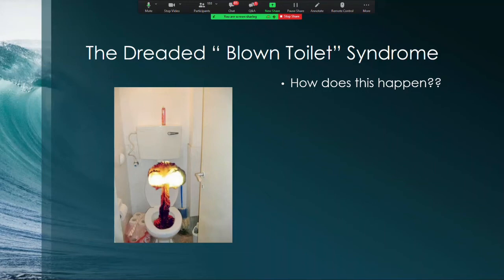So I'm trying to shove an 8-inch column of air through a 5 or a 4-inch orifice, which means that I compress the air between the nozzle and the debris. And once that debris goes by the service, Mrs. Brown's house, Mrs. Brown gets an unpleasant surprise because she provides me with a service line that is just basically a relief line, and it just blasts the air straight up that line. If the home is not properly or adequately ventilated, or there's an issue because there's something that's been blocked or whatever else, then the venting happens through the toilets and the floor drains. And this is where the majority, I'm talking 80 or so % of the blown toilets happen for this reason. There are other reasons as well, but some of those you just can't control. It's just a connection issue or whatever else.